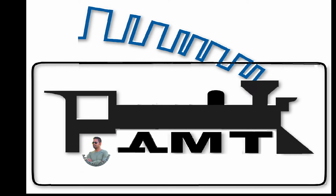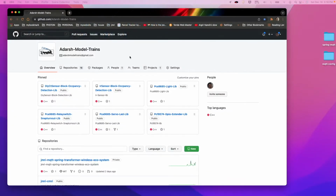So today we will see how we can configure light as well as servo based turnout using JMRI and REST API. So for that, first we have to go to github.com. So let's go to the GitHub repository.